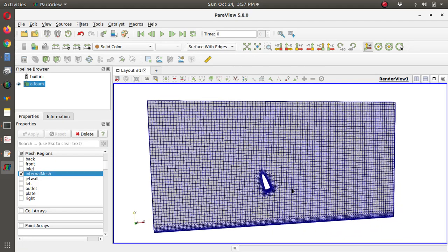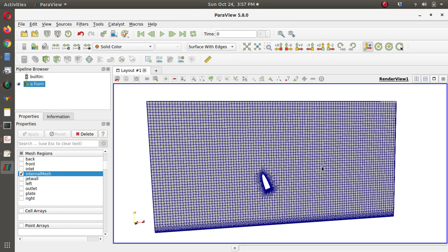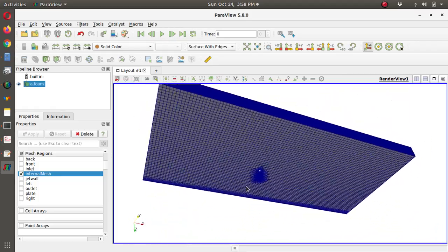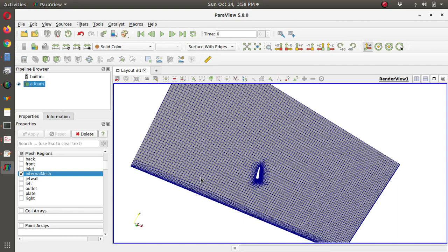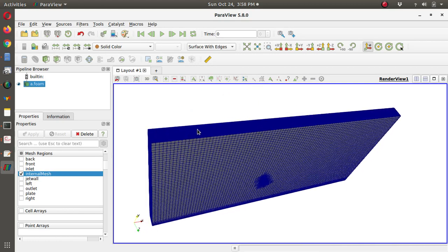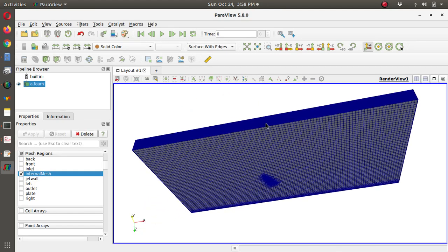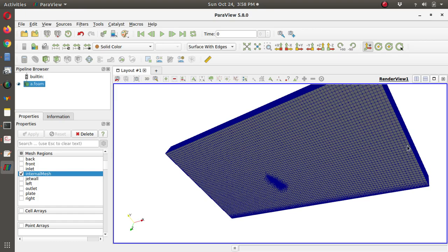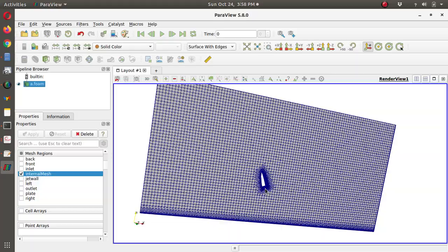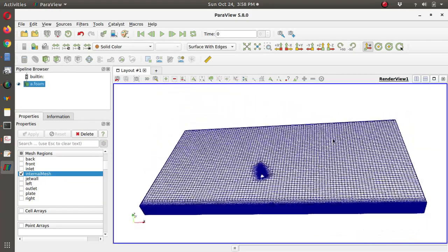So it is an excellent mesh, because we are getting very good structures of mesh, which will reduce the computational time. And further, in the next part of the video, we are going to put the boundary conditions at the different surfaces. This is our top surface, this is our right, this is the left surface and bottom, and there is a jet wall and jet exit. Everywhere we have to put some boundary condition.